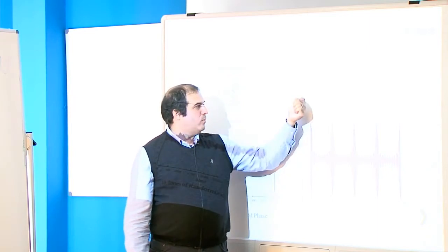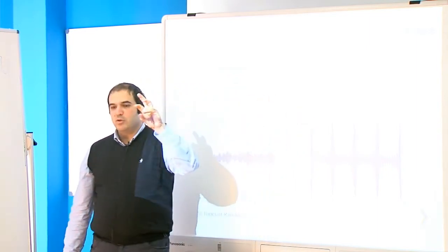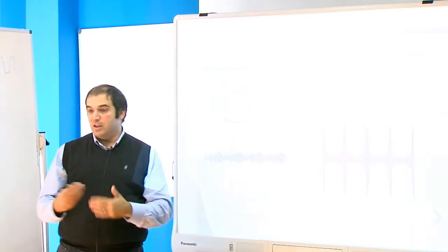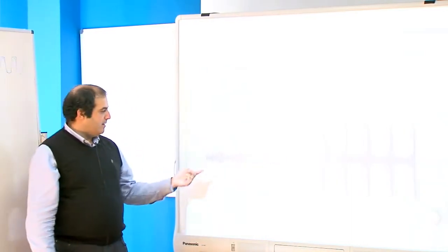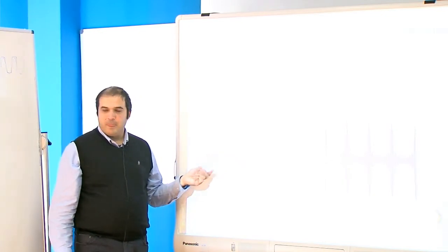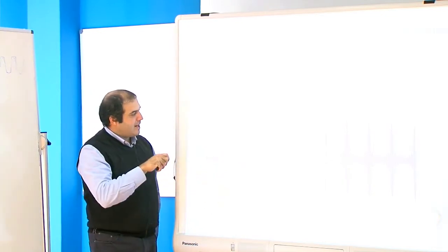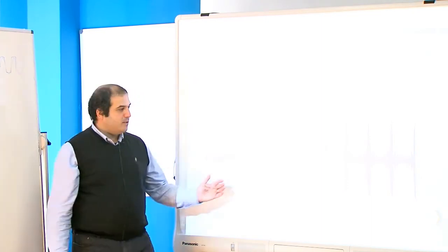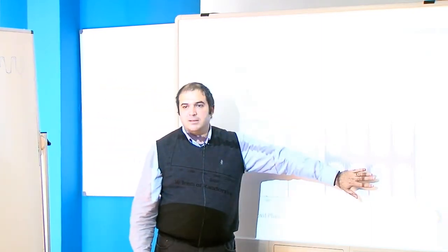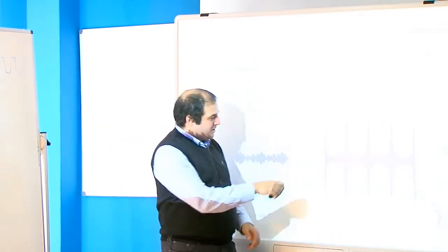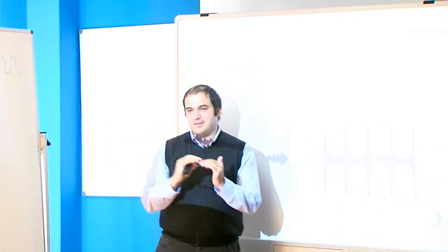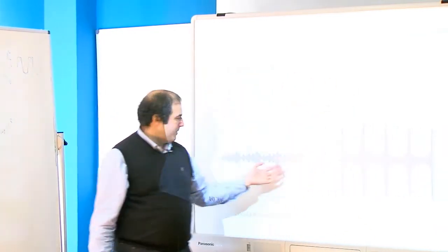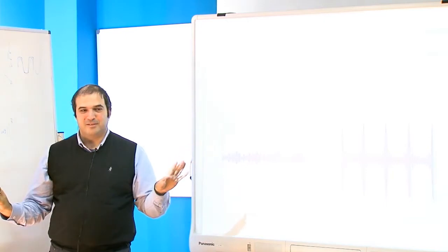Then I go with my formula and I choose the phases not 0 degrees but random. I put a random phase in each tone. And this is the output. Okay? This has exactly the same y-axis. What does that mean? It means that if I use this sign, imagine my transistor starts to compress at 4 volts. What will happen here? Huge distortion. What will happen here? Nothing, no distortion at all.